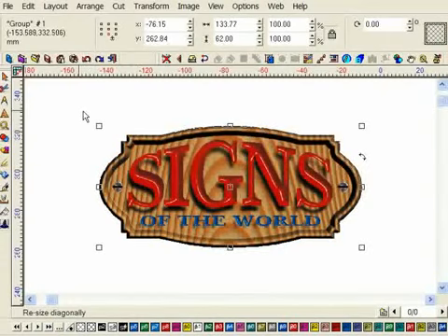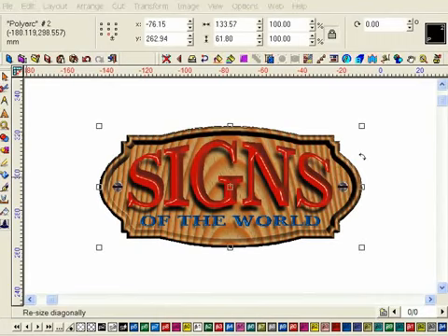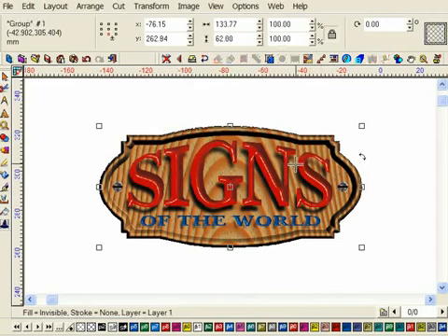The simplest way to achieve this is to apply the new half cut path to the contour line I just created. So in Synapse I'm going to select the contour. I can check I've clicked the right path by looking to the selected color icon in the taskbar at the top of the screen. When I have the contour line selected it shows black, and when I have my original object selected it shows invisible, because it's made up of a group of objects that have various colors and bitmap fills.